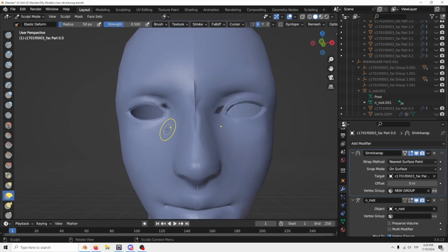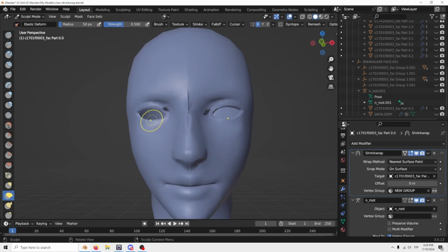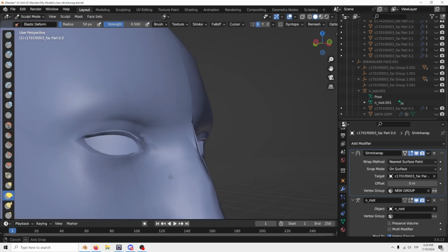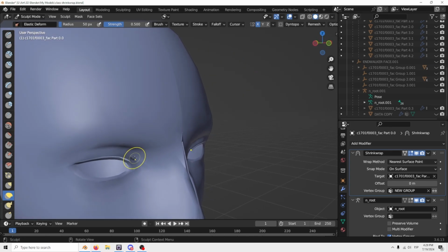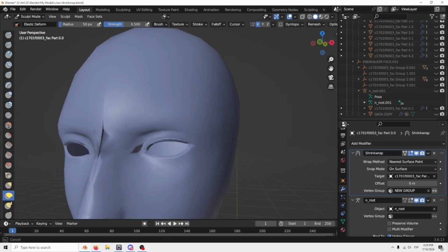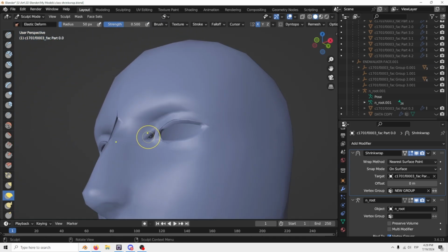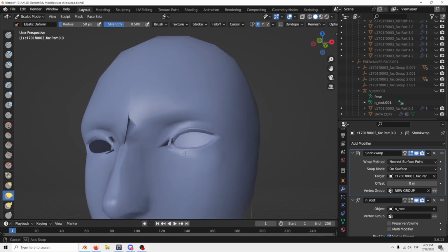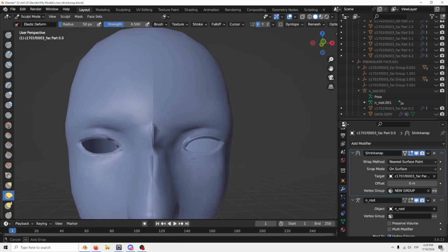For example, here, I see that there are dark areas over here. Then you can change into sculpt mode, and you can try to grab those parts of the face and just adjust them as necessary. Here the face also broke because of what I did, but just to give you an idea. And do some adjusting to see what makes the dark areas disappear, basically.